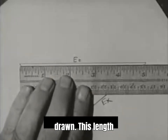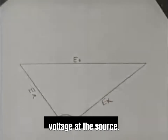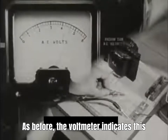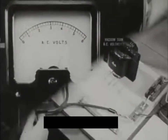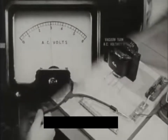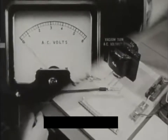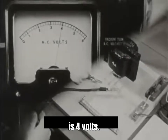Its length, 5 units, corresponds to the measured voltage at the source. As before, the voltmeter indicates this voltage as being 5 volts. This is true even though the drop across the resistor is 3 volts, and though the drop across the reactance is 4 volts.